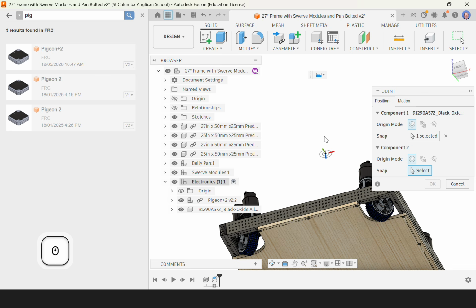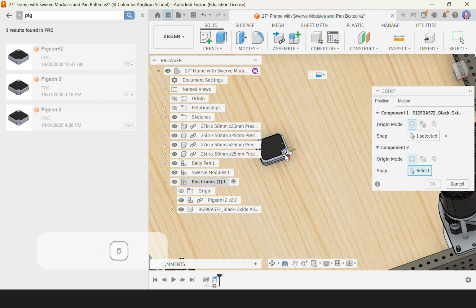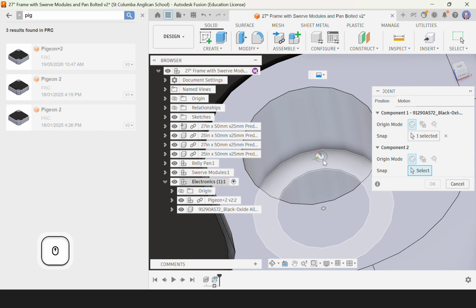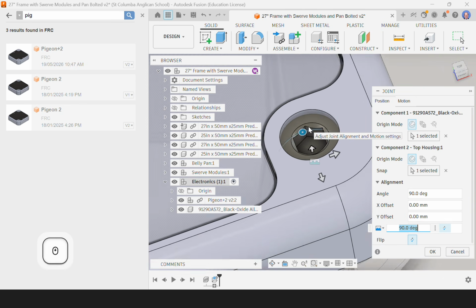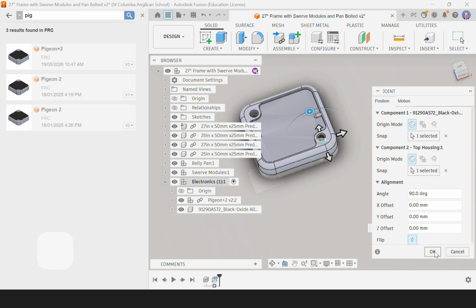All right, zoom that back out, pull the view around looking on top, zoom in here. And again, hover over that face that holds my joint origin, hold Control or Command on a Mac, come in there and grab the center of that circle. That's brought that screw, put it in place, and joined it there.